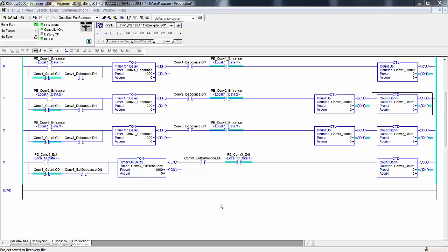You need to move the product in process through each station and see when the product arrives and leaves as it passes through each station. Within each station, you need to see each device that causes the progress of the product in process at that station. This would include the individual actions of each device, cylinders, motors, you name it. At this level, you are experiencing presence and action, sensors and actuators.